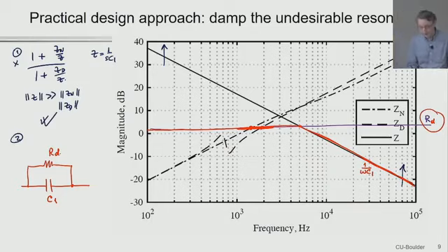It's the power dissipation. You're going to have a DC voltage across this C1 in the SEPIC converter. In fact, that voltage is going to be equal to the sum of the input voltage and the output voltage. Lots of DC voltage across that component, and then you place a resistance of RD in parallel with that, and you just dissipate power. It kills the converter, really.